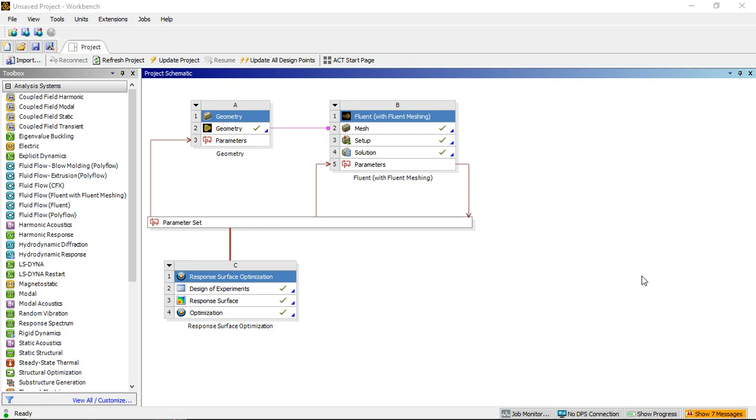I have used an 18650 lithium-ion cell, and around the C rate of 0.8, or something like that. I'll discuss it in detail in further videos. To model the heat generation, we'll use forced air cooling strategies to cool the lithium-ion batteries and the whole battery module system.